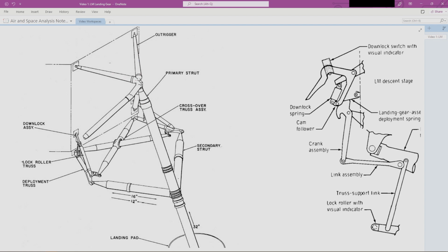They could have just sent this one straight to the middle, and then you do have a nice symmetrical loading structure here. But then you have a fair bit of your load going right into the middle of this panel, not all of it, because it's split between tension in these members and compression in this member.